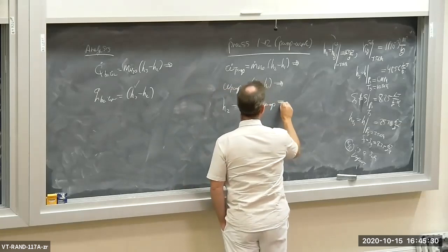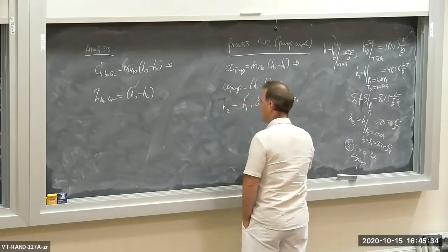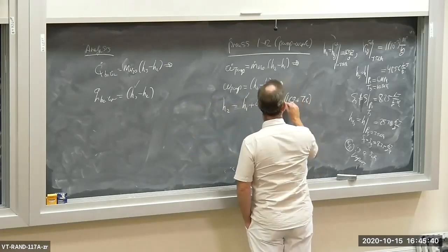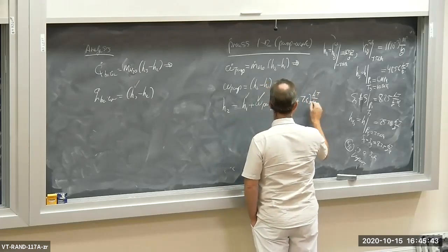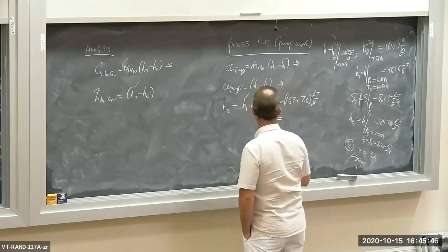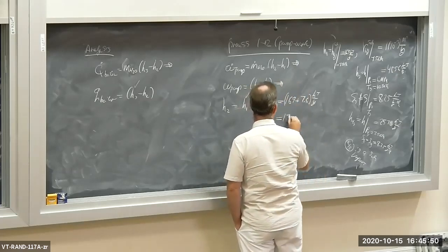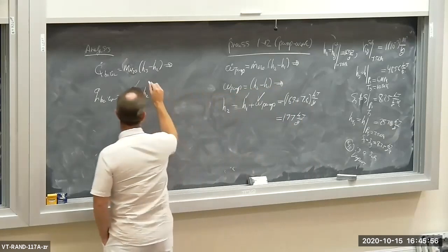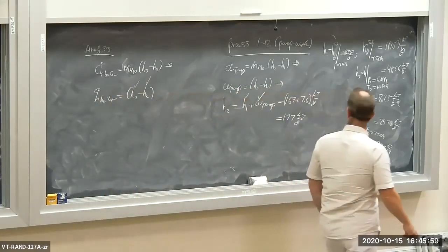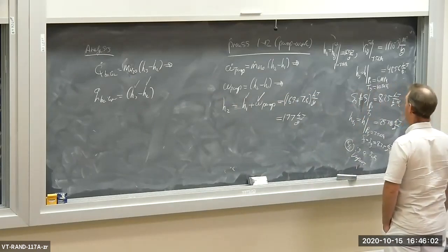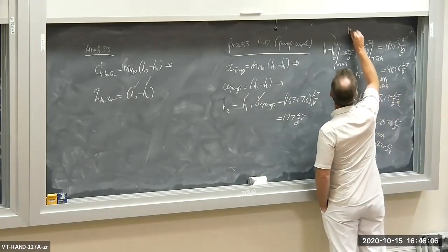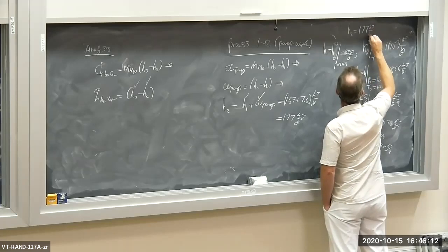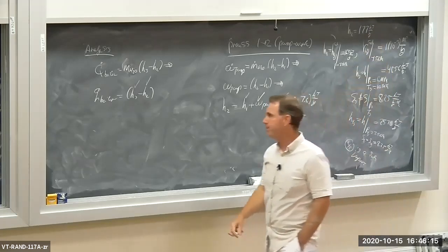Check, excellent. Let's see here, 169 plus the specific pump work, 7.6, which has units of kilojoules per kilogram. So basically, I'm just going to round up here. This is 177 kilojoules per kilogram. Okay, now I have H2. In fact, I'm going to write that somewhere, right up here. H2 equals 177 kilojoules per kilogram.